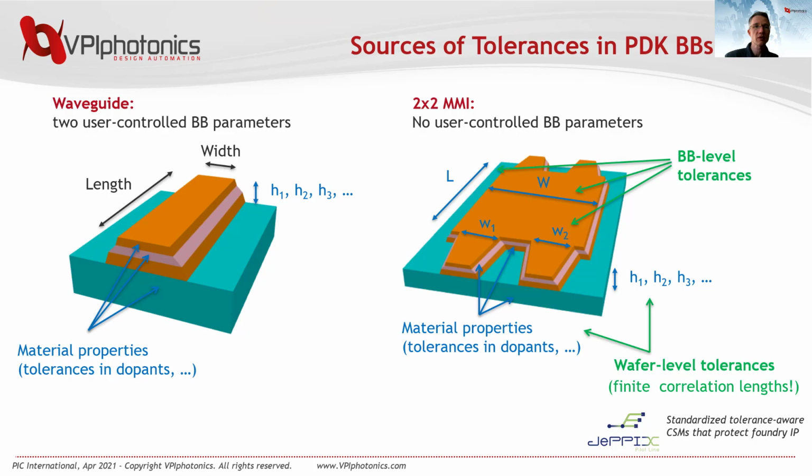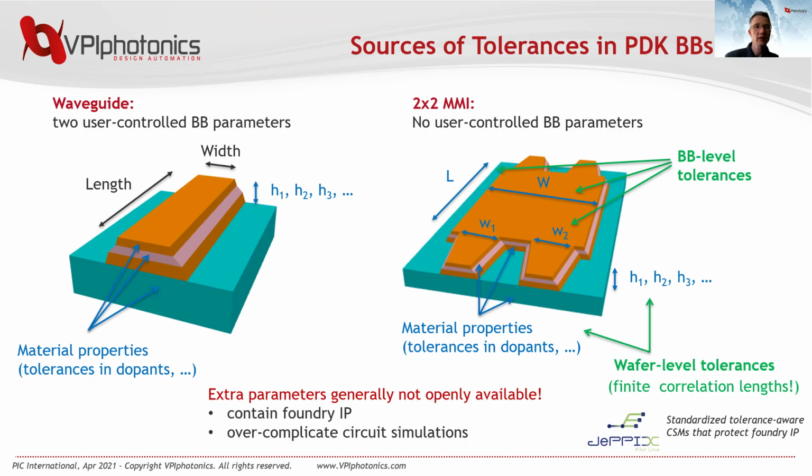Moreover, some of these parameters are directly related to the module, while others might refer to the wafer they are produced on. Any of such parameters cannot be utilized by the user directly. This would disclose the foundry intellectual property and furthermore make circuit simulations overcomplicated.